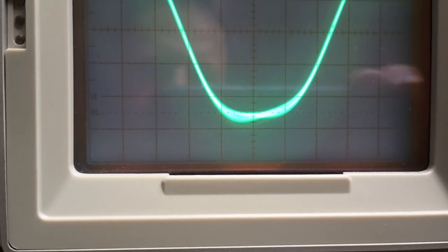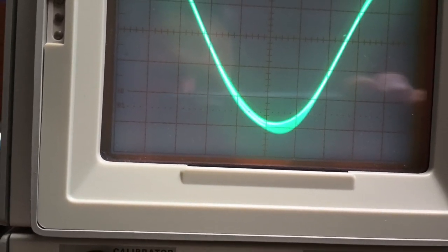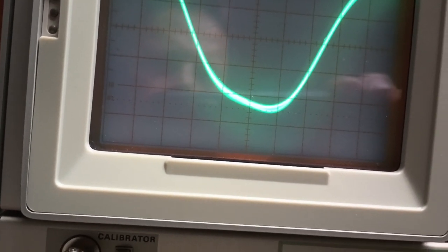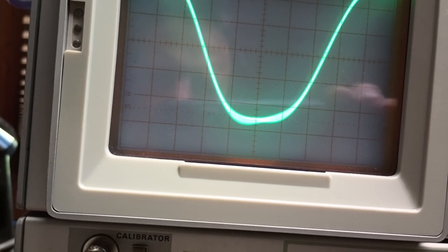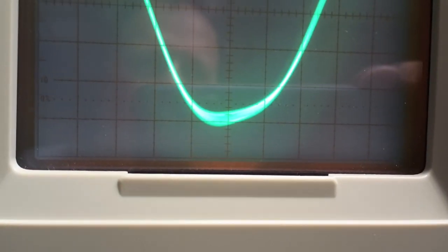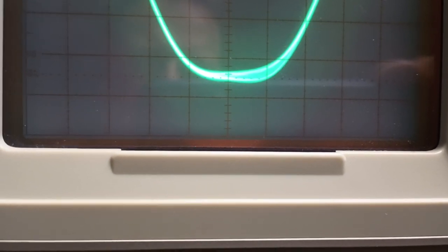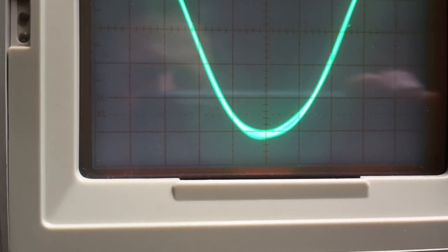But watch what happens. See how you can see a hump shifting? Big time. There's a hump over here that's changing. If you watch kind of closely, you can see them separate. Now they're kind of both the same amplitude. One's to the right, one's to the left. That's 20.8 megahertz, 20.9, 21.0, 21.1, 21.2, 21.3. This antenna is pretty flat up to 21.45, real flat.